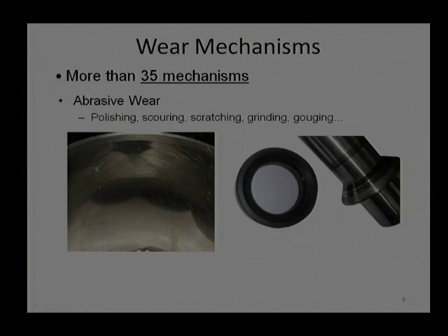If the surface is textured to retain the lubricant, the texture will be removed, and if that texture is getting removed, we are losing performance. If I say some sort of diamond shape is given to the liner to retain the lubricant, as storage, and if those diamond shapes are getting polished, naturally the performance will come down. Whatever we optimize the surface to retain the lubricant properly will be removed. Some other performance will come because the polishing is going to generate some other surface, some other roughness parameters, which may not be optimal. Naturally, because of that, some problem will come.